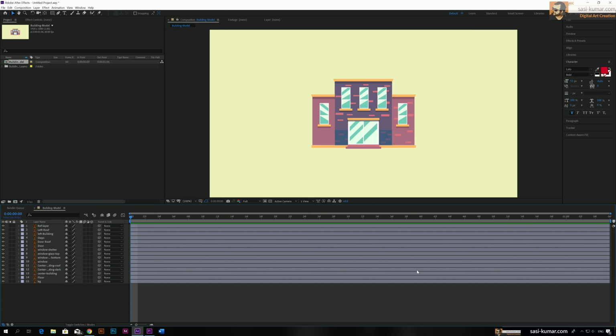The first part will come from the bottom, the second part is the idle stage where the animation won't do anything, and the third part will be the reverse of the first part, where all these parts go below. What I'm only going to do now is animate the first part. For the second part I'm just going to place the model there, and for the last part, I'm going to reverse the same animation I created in the beginning and put it into the timeline.